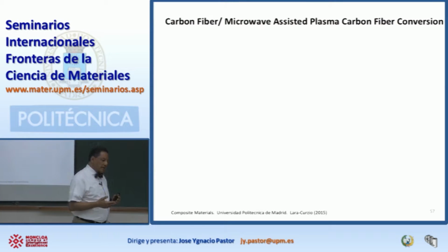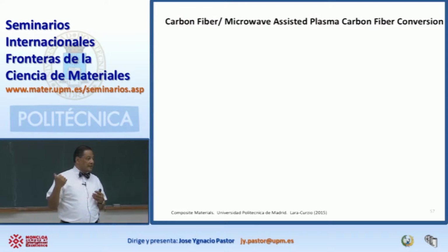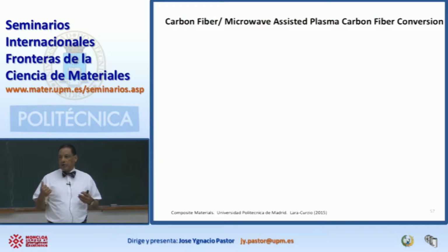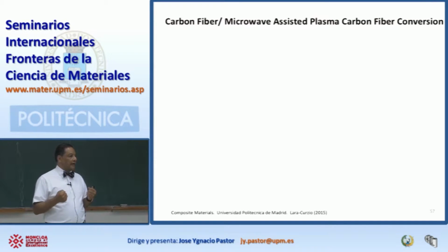So if you're going to be making an airplane, and I'm going to show you an example of how Boeing uses this type of materials to make the 787 or some military aircraft, these components are subjected to large mechanical stresses. So the stresses are first applied to the matrix, and then the matrix transfers those stresses to the fibers. And that transfer of stress happens at the interface.